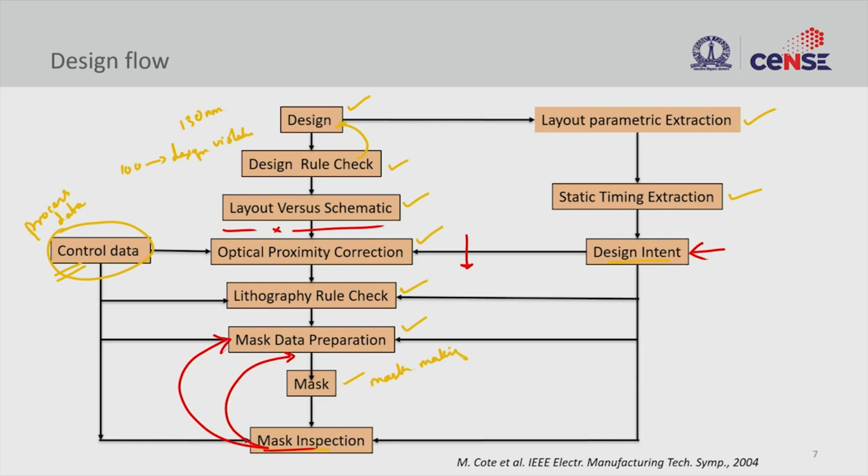So it is very important that there is a closed communication between the designer and your mask preparation team, so that you get your desired circuits fabricated that will yield the required parametric performance as well, not just the structural yield. You may just have a line, but whether the line is of required resistivity matters if you are going to look at the timing.